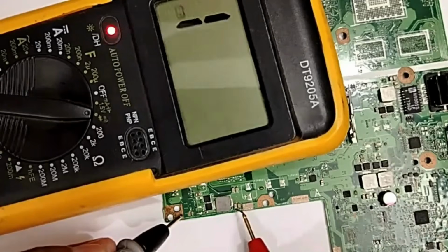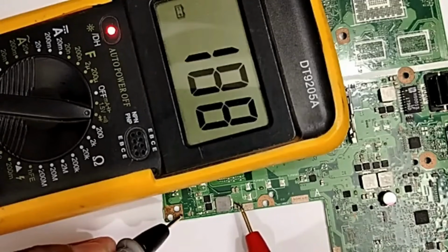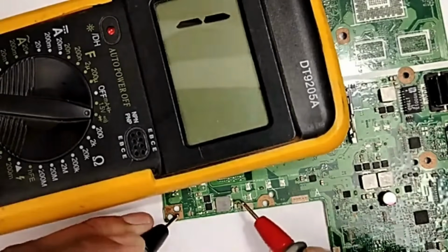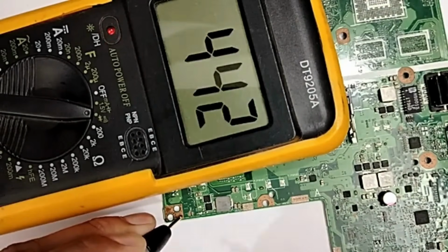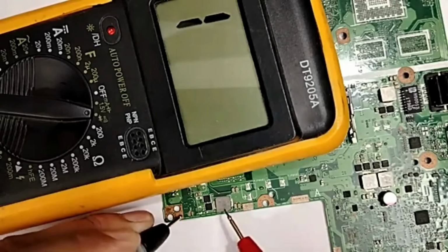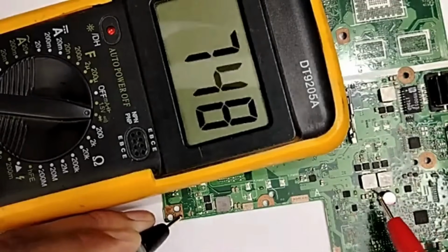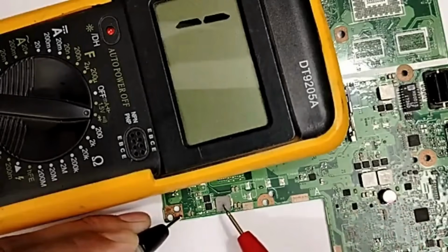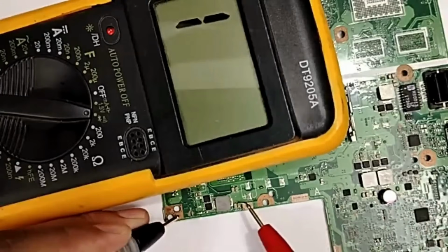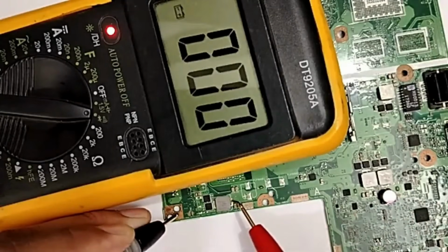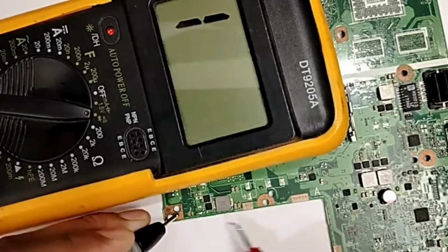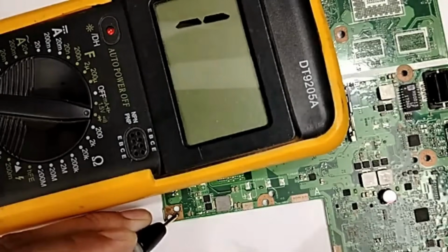Oh, we have a shorted capacitor. No, we have a short here, guys. This is a short. Do you see, my friends? This is a short because, as I told you, the inductors can never be connected to the ground, as you can see. Never. But for this inductor, with one probe in the ground, we check this inductor, 0 in the multimeter. This is the short, guys. This is the real short. 0 means we have a short here. This is good, very good.